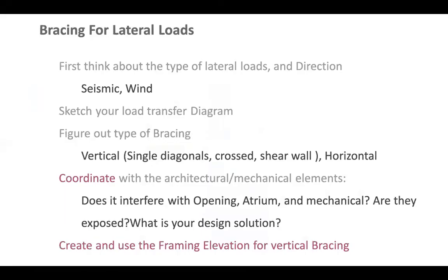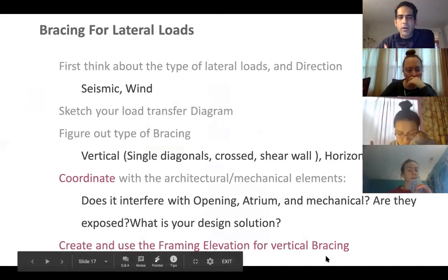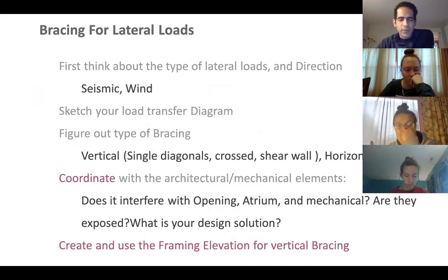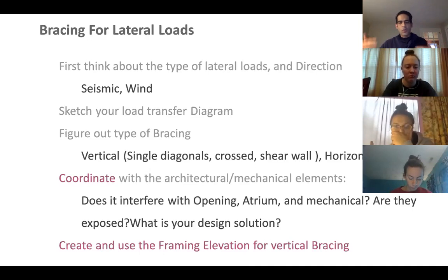All right, so yesterday we discussed this. The other piece that you have to think about is obviously the lateral bracing of the building. If you remember, we discussed that you're trying to avoid torsional irregularity in your building. That's a very important part. That means the way that you distribute the bracing for lateral loads, you have to have it for both directions, and you have to place them so that, toward the center of your building, they are symmetrical. That's a very important piece, where you want to place them.